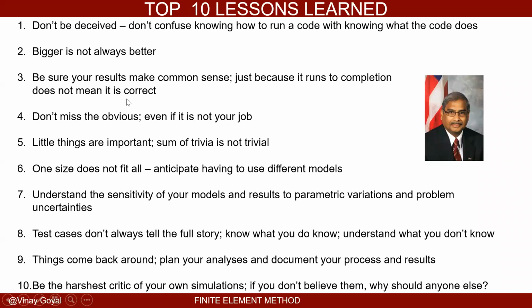Okay, these are some of the lessons learned. Don't confuse knowing how to run a code with knowing what the code does. That means if you can run something on Nastran or Abaqus or whatever, don't assume that you know what the code is doing. Bigger is not always better. Be sure your results make common sense. Just because it runs to completion does not mean it is correct.